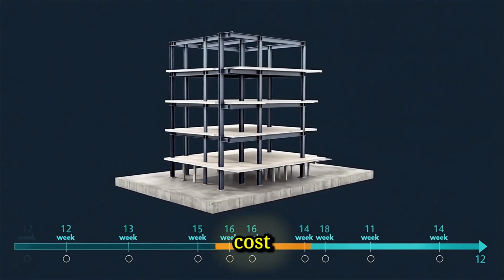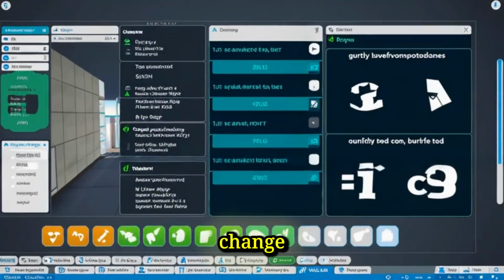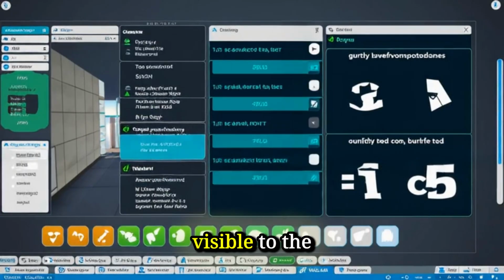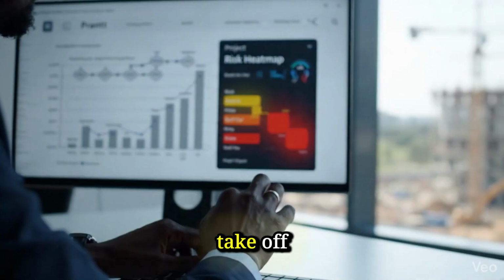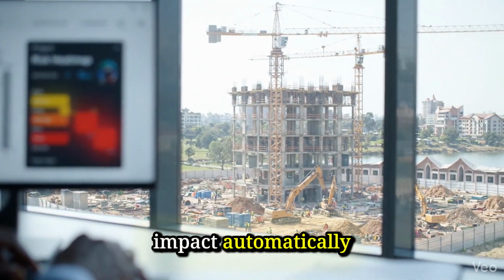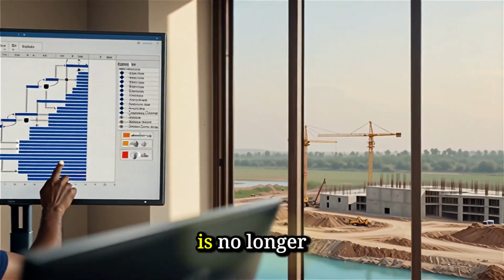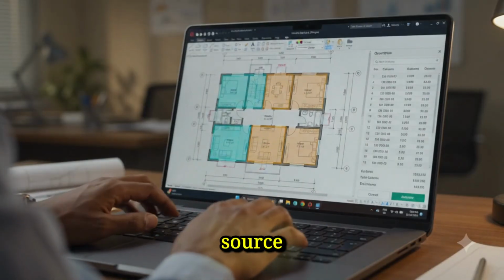5D BIM adds cost. Connect the model elements to cost data, and every design change has an immediate budget implication visible to the whole team. A wall specification change updates the quantity takeoff, updates the cost plan, and flags the impact automatically. The quantity surveyor is no longer running to catch up with the designer. They are working from the same source.